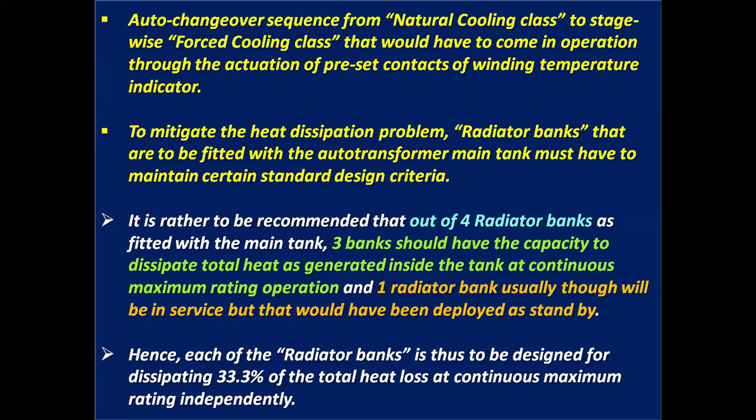Each radiator bank would have to be designed in such a way that it dissipates 33.3% of the total heat loss at continuous maximum rating independently.